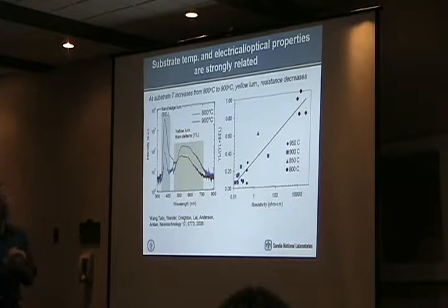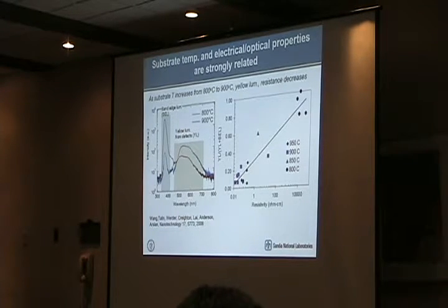Now, as I mentioned, what we do is we use MOCVD, meaning that we have a source of carbon. A number of people don't use MOCVD. They just flow ammonia over a little container of gallium that's placed upstream from their susceptor. And so the ammonia reacts with the gallium, transports to the susceptor, there is a catalyst, and a nanowire grows. Mark Reed's group did extensive studies of these nanowires.